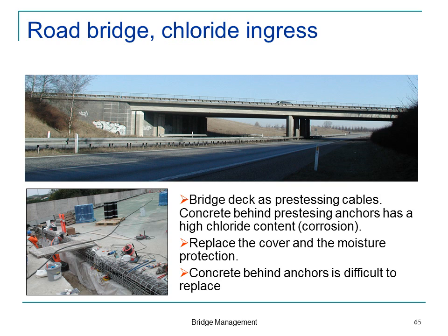We had, for instance, a case with a railway bridge. There was a lot of chloride ingress. That was not really the problem. The problem was the chloride had penetrated so far that it had penetrated in behind the anchors for the pre-stressed reinforcement. And we did not wish to remove the concrete behind these anchors, because we would be in serious trouble.